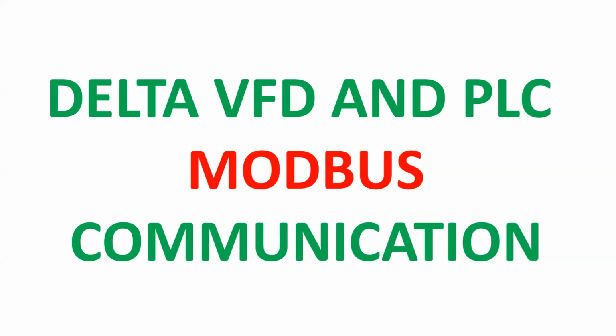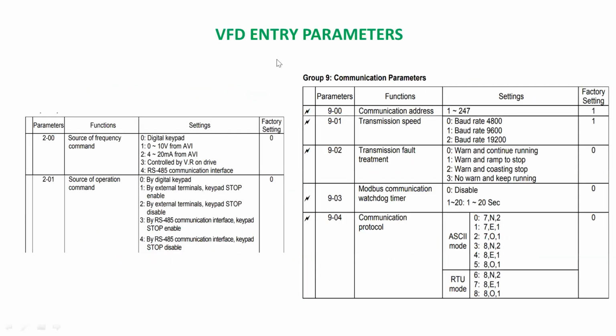That's why each and every PLC has certain Modbus protocol relevant register memories, and the VFD also has its own register memories. We need to analyze everything and then move on to the practical. First, we need to go to the VFD here.